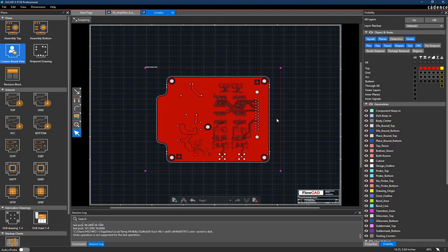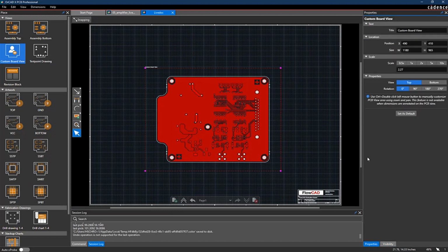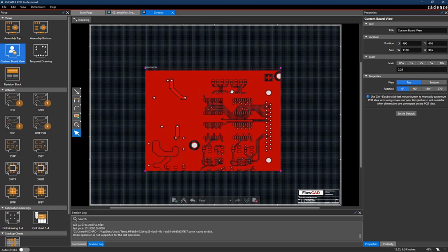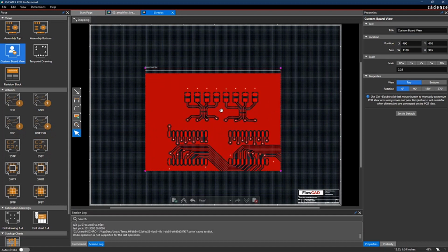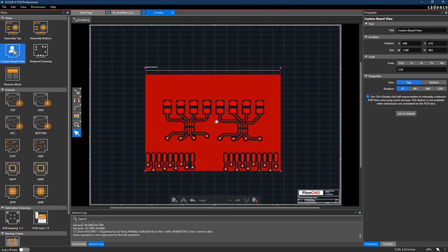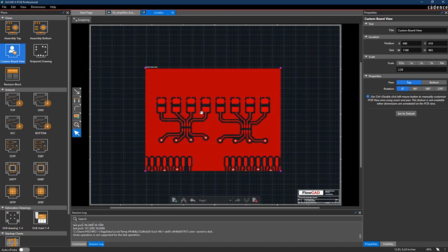What is also a nice feature, though honestly a little bit strange to use, is that you have some hints regarding this. There's a feature to zoom in and have a detailed view of your design. For that you need to press Control and double click, and then you can zoom in. We can see these two ICs on top here with their blocking caps or whatever components these are.